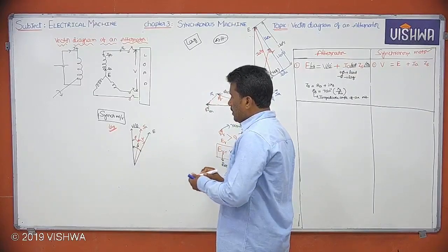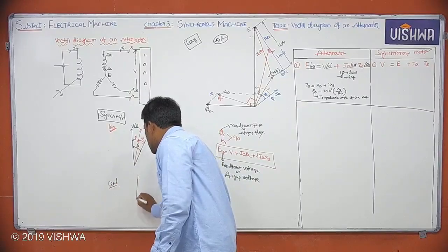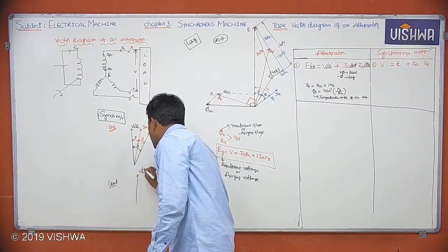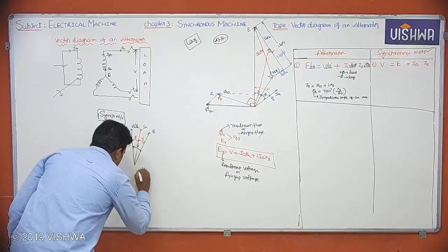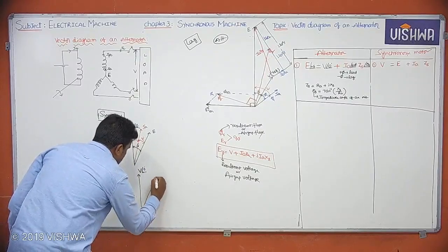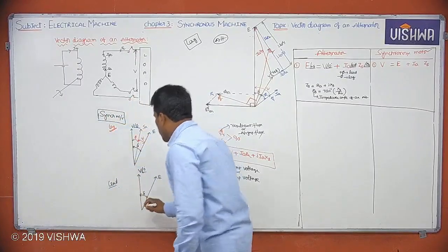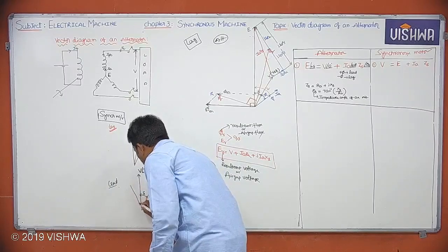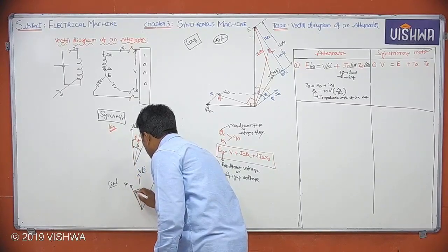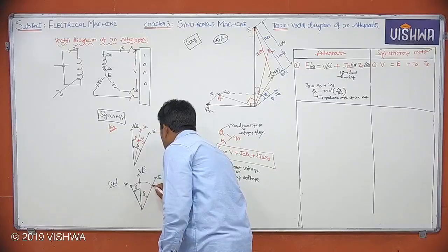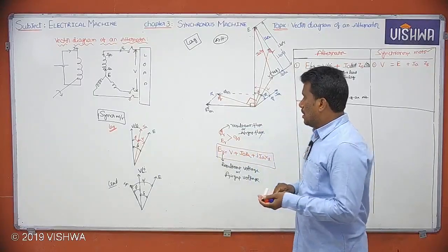So please tell me, for lead loads, how, like this, what your V reference, and EMF E lags by an angle of delta. Leading, synchronous motor operating leading power factor. So I can take Ia leads V. What about this angle? Phi. Angle between Ia and E, how much? Phi. Is it clear?